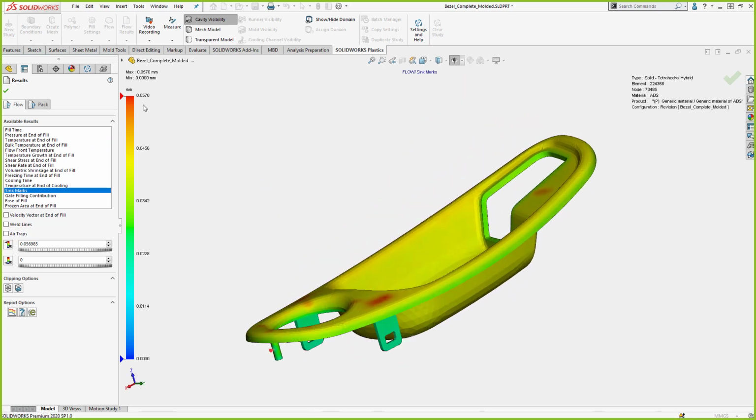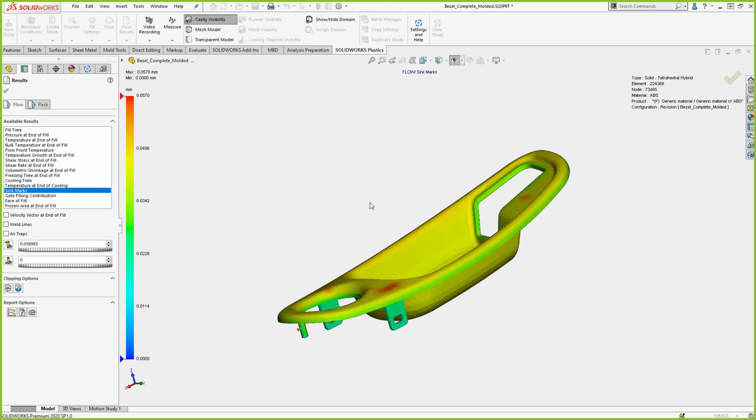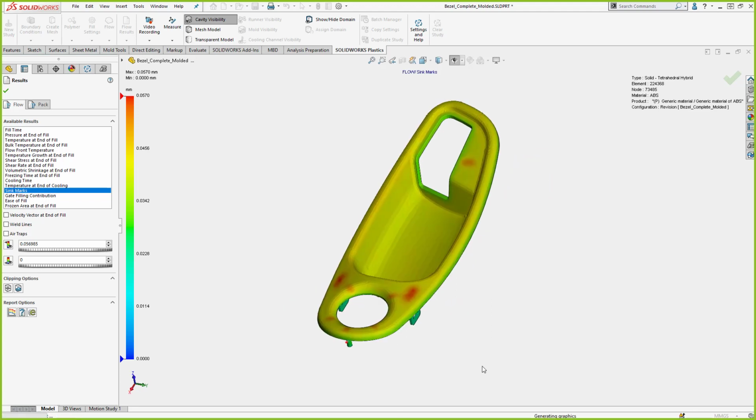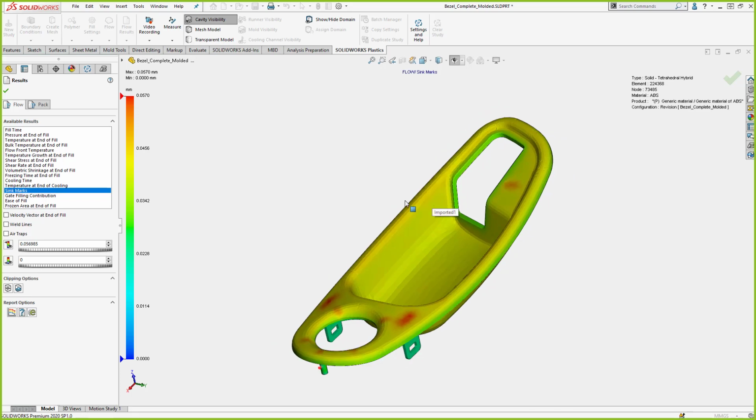So in this case, let's look at our sink marks on this part model now. Remember, we were at 0.127, now we're at 0.057. So we cut it down from approximately 5/1000ths of an inch to around 2/1000ths. So it cut down quite a bit. This is something, if we would have run the analysis prior to having this mold built, we would have saved that cost of change.